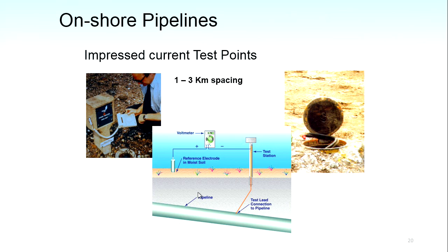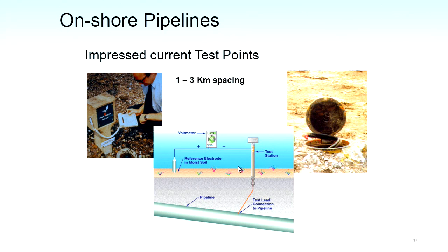Okay. This is the anode installation side of things. Basically, you've got two options. You can either lay the anodes out horizontally, sort of parallel to your pipe structure. Often the pipe will be tens of meters away from the anodes, and we'll discuss that a little bit more later.